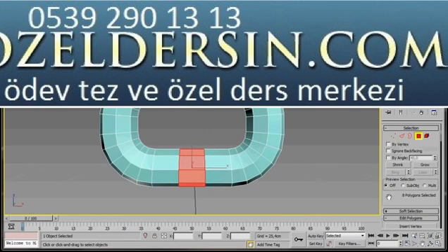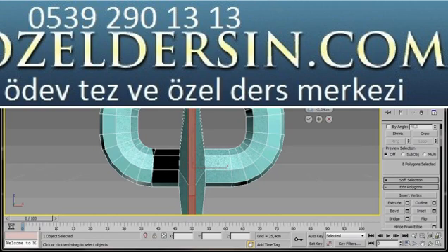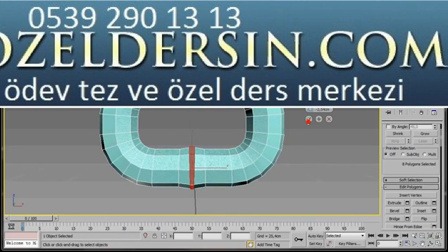We're going to give them a bevel. So let's come over now and select the small settings icon for bevel. Okay, we can see our default settings. First of all, we'll change our group. Select Local Normal. And now here in the bevel height, we'll just bring it down to something like 0.5. Now in the bevel outline, we'll bring this down to a -1. Then press OK. That's giving us a nice little bevel here.